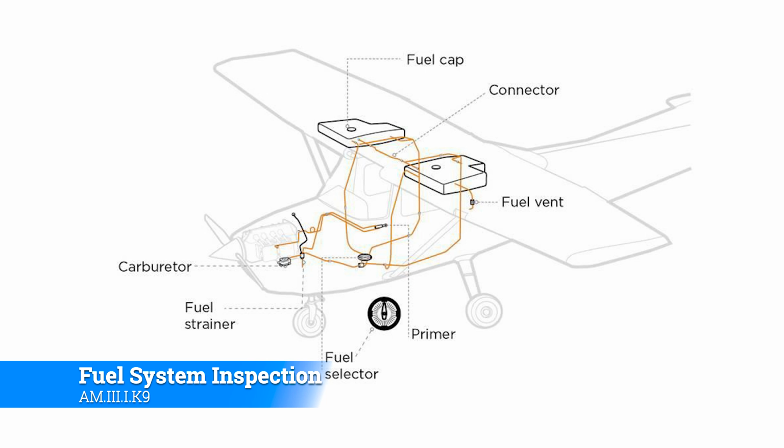So if you've got any boost pumps that are installed, the system should be checked for leaks by the pumps. Those pumps are known to start leaking. They'll also set up over a period of time and then start to crack. So you don't want to have that at all. You'll run the boost pumps and you'll check the amp meter, make sure that the load meter should read and have all the readings for all the pumps. That way you can actually see the pumps kicking on, the amp meter showing that, hey, look, there's amperage going out. That way you know that it's working.